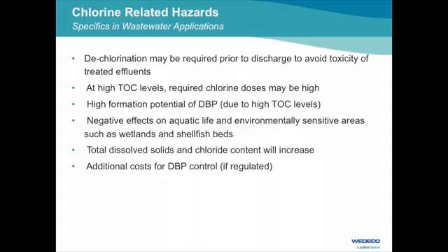On the other hand, chlorine is very dangerous to aquatic life, and if you have sensitive wetlands or fishing areas, you may want to reduce the residual content before you discharge the wastewater into your receiving water bodies. This is becoming more and more regulated. I've seen that even for South Africa there is a guideline that you should discharge zero chlorine, at least for some special waters. This would mean that you need a dechlorination step after you chlorinate, which again adds to the cost of chlorine dosing.